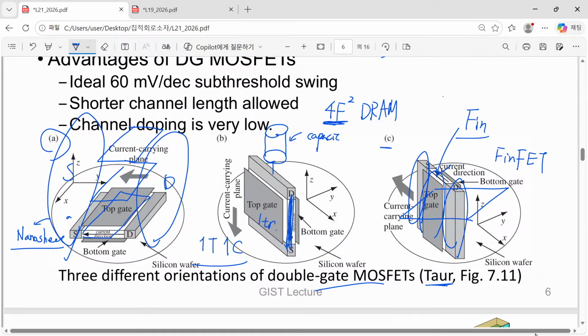So actually in lecture 20 I have shown how we can fabricate a fin, actually a set of fins, by doing certain fabrication steps. Maybe you remember that after all kinds of complicated etch and deposition, finally we generate parallelly placed structures, and each of them is called a fin. And by placing gate, source and drain on that fin, the transistor becomes a FinFET.